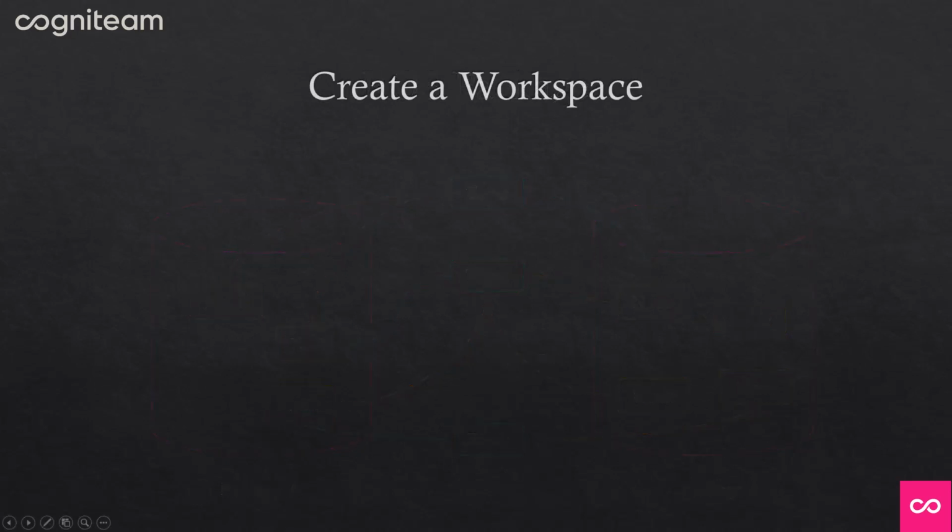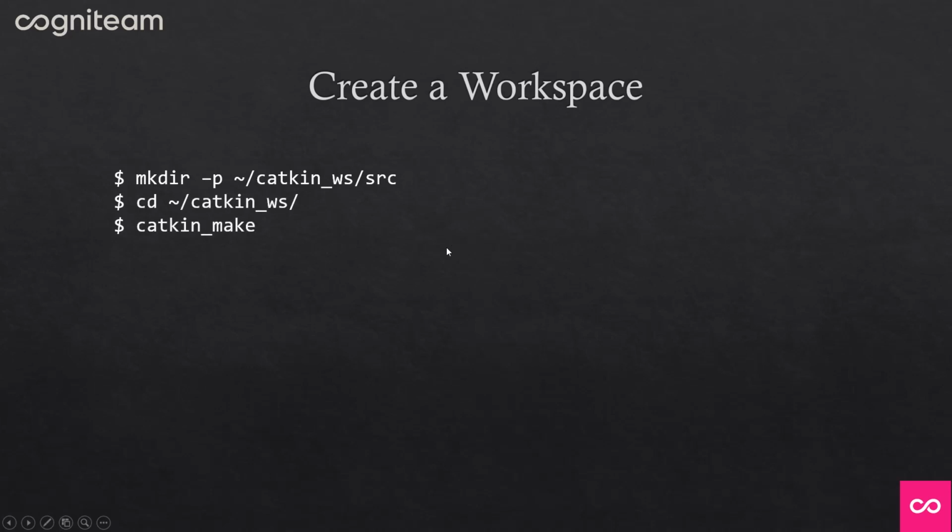Now we need to create a ROS workspace. You can just run mkdir to make a directory called cogniteam_workspace/src. Then you can go into this directory and run catkin_make. catkin_make will use cmake in order to create a template folder for your workspace, and you will have these subfolders: build, devel, and src. I invite you to go to the ROS tutorials to learn more.